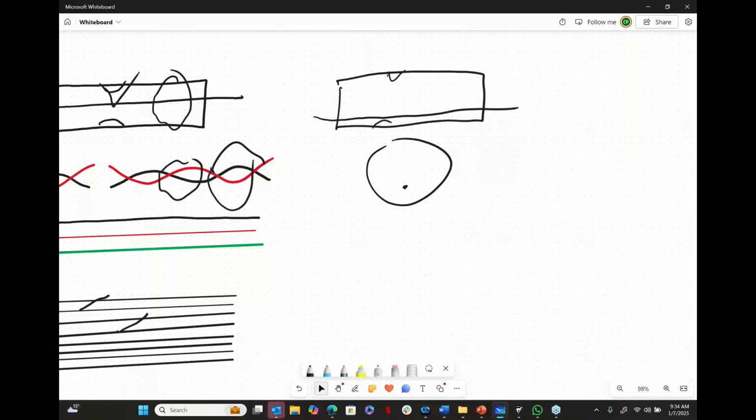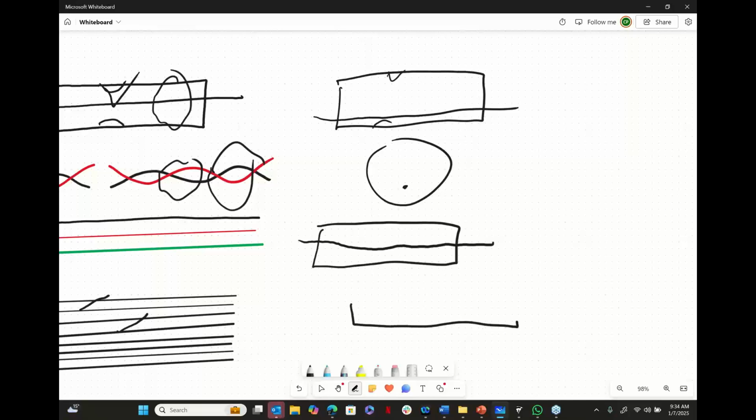Now, where this can cause a problem, what if you have a fire? Oh, yeah. You get a fire, of course, and then if that dielectric melts and this happened, will a TDR see that as an issue? Most times, yes. But what about this? What if this distance that I'm talking about here, what if it's a 30-foot section of cable, and what if it is ever so gradual over 30 feet? Will a TDR see that? That's where it becomes some of the harder stuff to find.